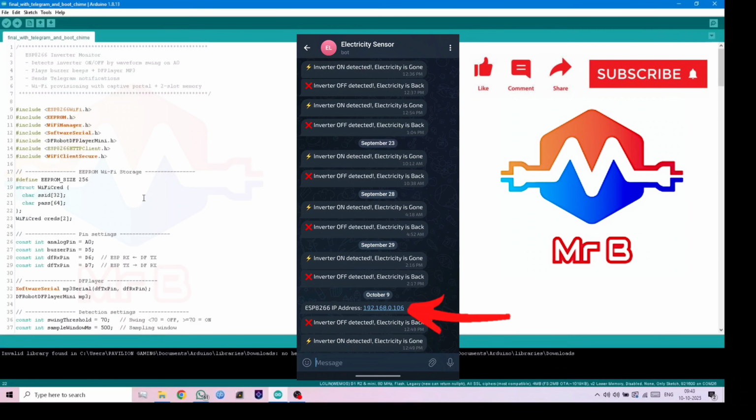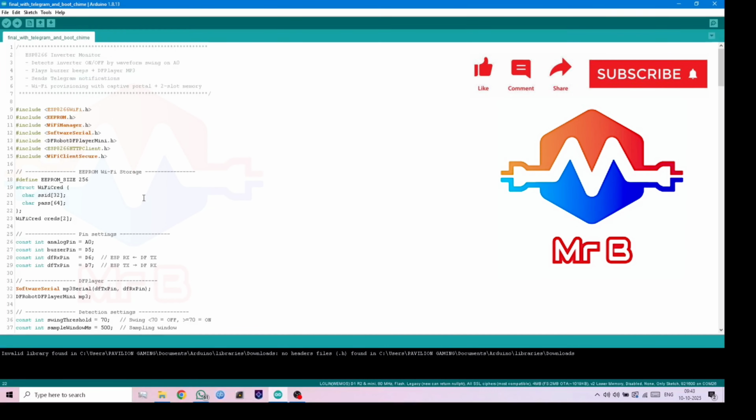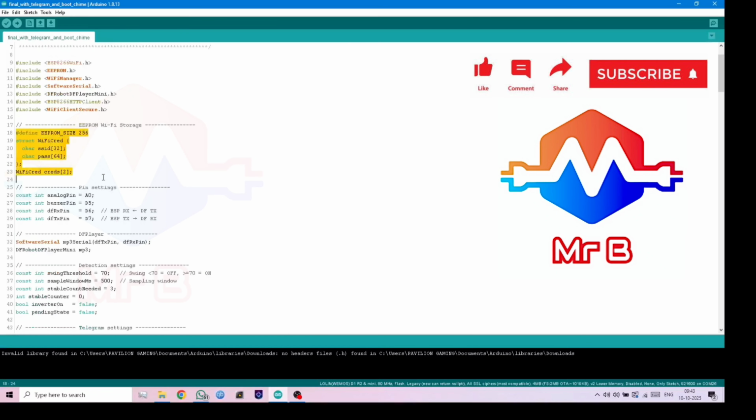I'll throw up a screenshot here right now. You can go into that IP and then put in the Wi-Fi credential, which it will store in the EEPROM of the ESP. And for the second boot up or the subsequent boot up, it won't require this step anymore because it has saved that Wi-Fi credential. This is only for the first boot up after flashing. Okay, so this is that part.